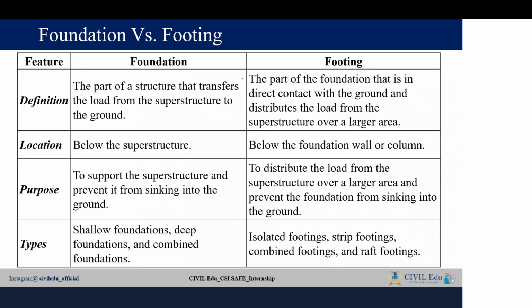Let me tell that in a much different way. By definition, foundation can be defined as the part of a structure that transfers the load from superstructure to the ground, whereas the footing is a part of the foundation that is in direct contact with the ground. The footing helps to distribute the load from the superstructure over a larger area, that is the subsoil. The foundation will be there below the superstructure, whereas footing will be there below the foundation wall or a column. We have the foundation walls, I'll show you those images in some time. So below the foundation walls, the footings will be there.